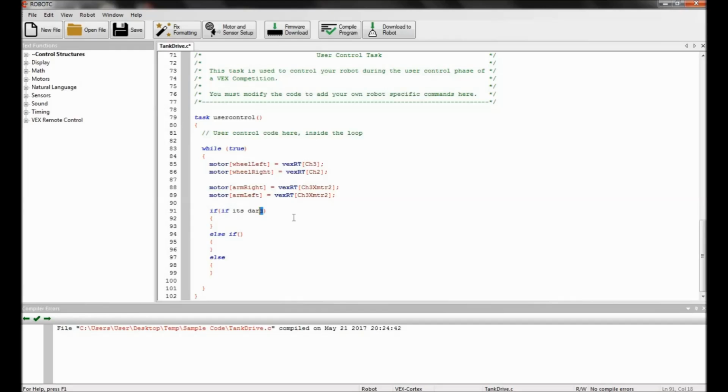For programming the claw, or just buttons in general, we use very similar logic. If the button is pressed, which is your condition, the response will be to set the motors to a specific power level. The reason we have three branches is because there are three conditions that the claw can really be in at any time: open the claw, close the claw, or have no movement.